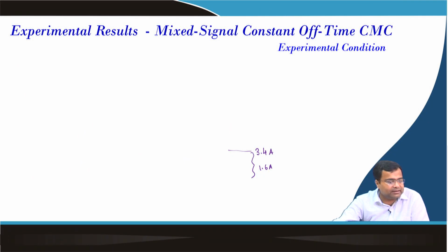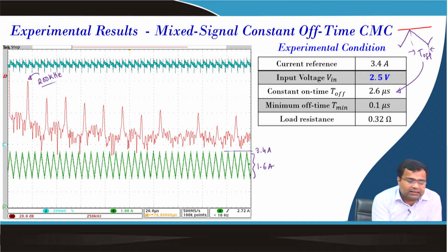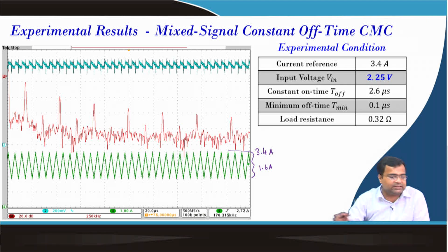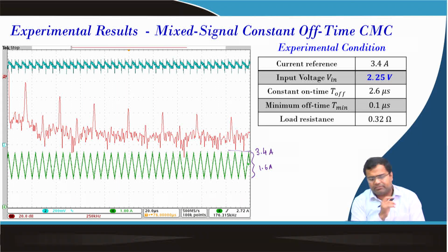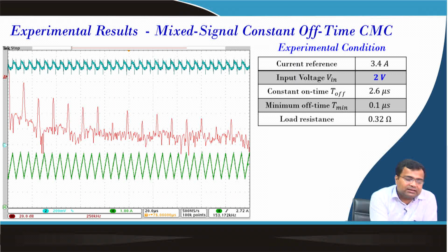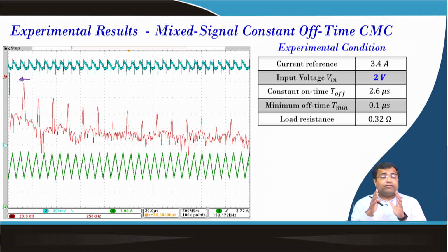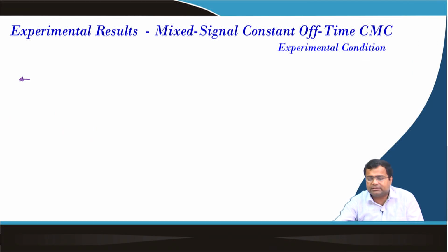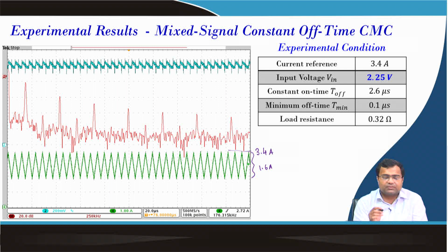But what you will find here, the peak was coming in the second dot. Now here you will see it is slowly shifting, but not perfectly visible. If you go next, this peak is shifting towards this side, which means the frequency is decreasing, because we have further decreased the input voltage, but it is perfectly stable.